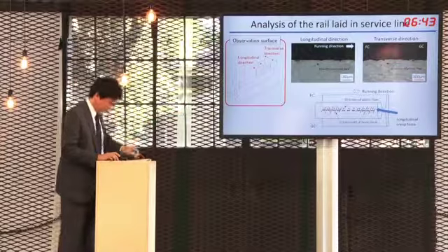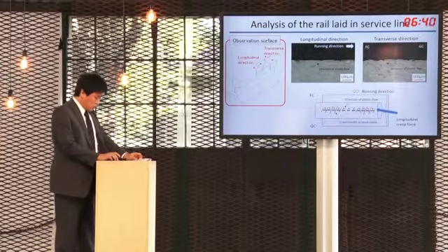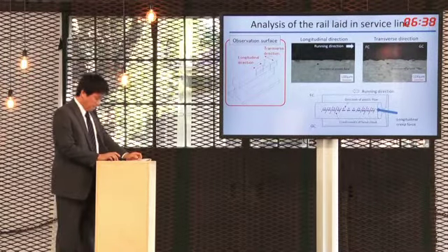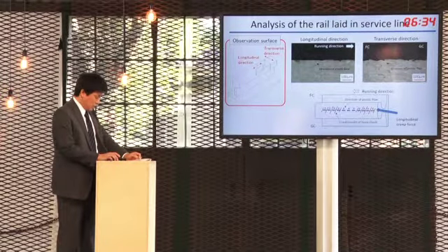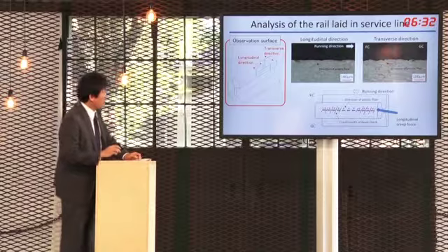Therefore, the plastic flow under the rail surface was confirmed in the rail for analysis, which has the head check on the rail surface as shown in this figure. According to the directions of plastic flow, it is thought that the longitudinal creep force affected the head check appearance.